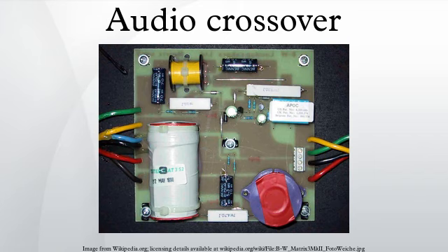Second-order filters have a 40 dB decade slope. Second-order filters can have a Bessel, Linkwitz-Riley or Butterworth characteristic depending on design choices and the components used. This order is commonly used in passive crossovers as it offers a reasonable balance between complexity, response, and higher frequency driver protection. When designed with time-aligned physical placement, these crossovers have a symmetrical polar response, as do all even-order crossovers.